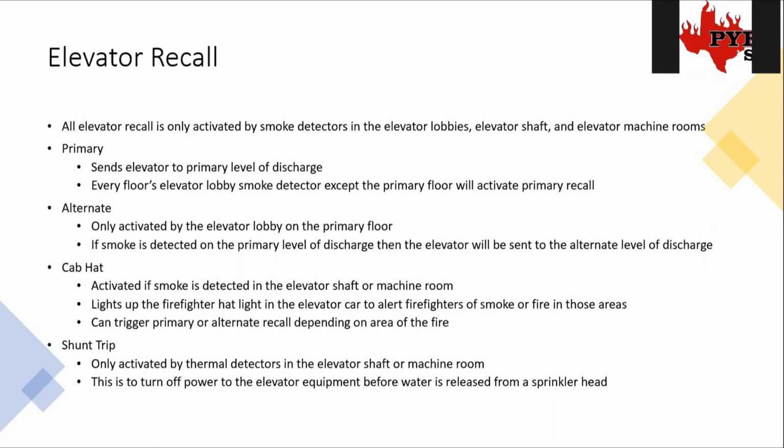And then the last one is a shunt trip. This is pulling power away from the device, because these elevators are powered by 480 volts. So we want to pull power off of it before water hits it, because water and 480 volts don't mix very well at all.